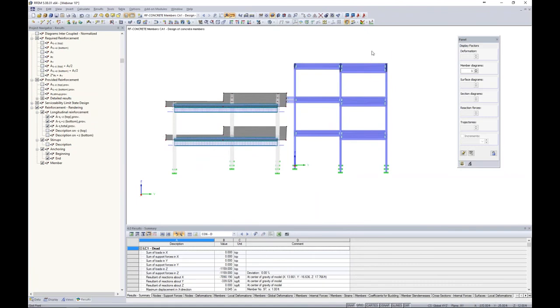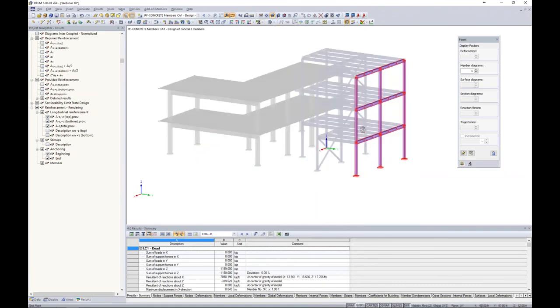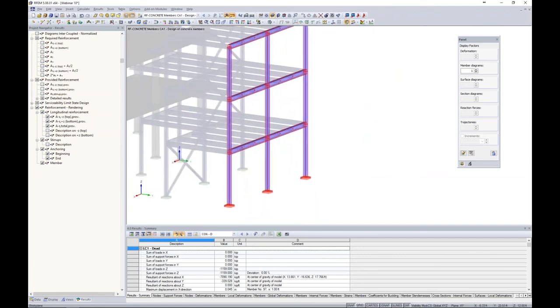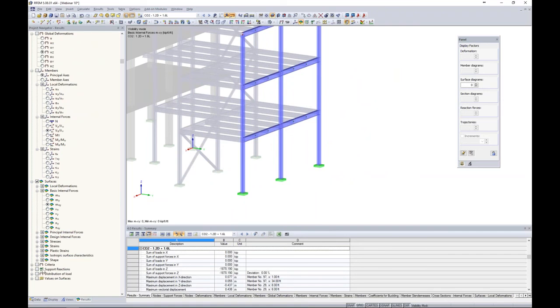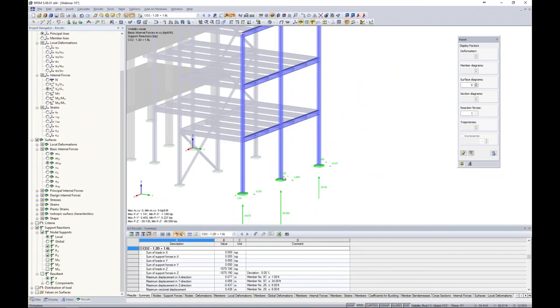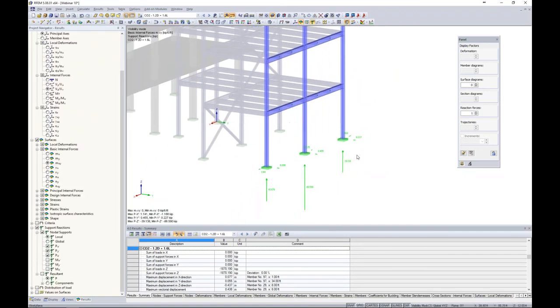And just a nice feature to show you is maybe we select this column line and show our visibility by our selected objects here. I can zoom in, and I'm going to jump to one of my load combinations. Here I'm going to display my support reactions, and I'd like to print off this picture, but I'd like to do it for all of my load combinations.